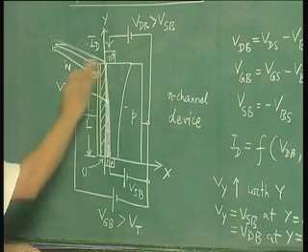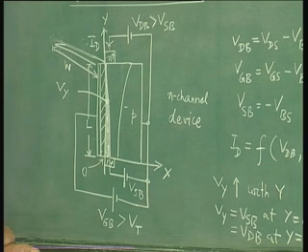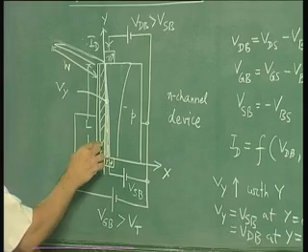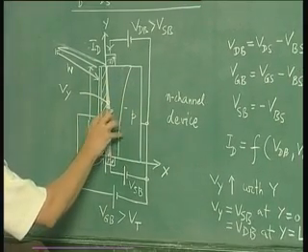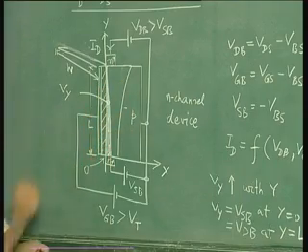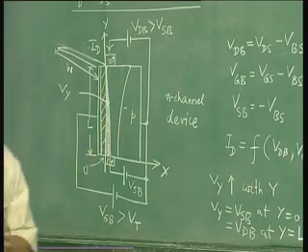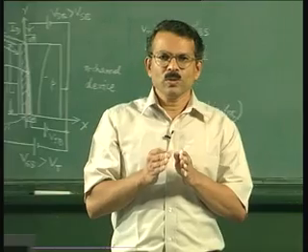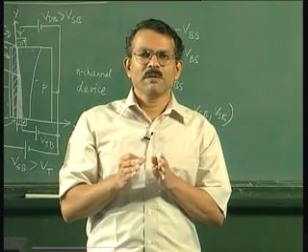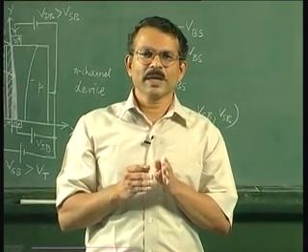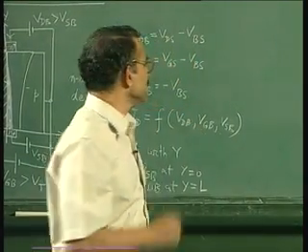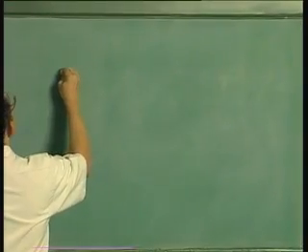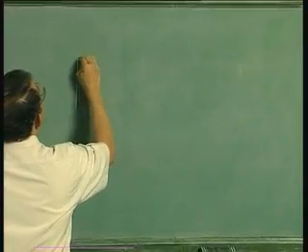Now based on this charge picture, we must derive the current voltage characteristics. So now we will show a simplified diagram showing only the variation in the charges in the MOS capacitor, and see how when you change your drain to bulk voltage, the current goes on increasing, but then after some time it saturates. So for this purpose, let us draw a simplified diagram as follows for different drain voltages.